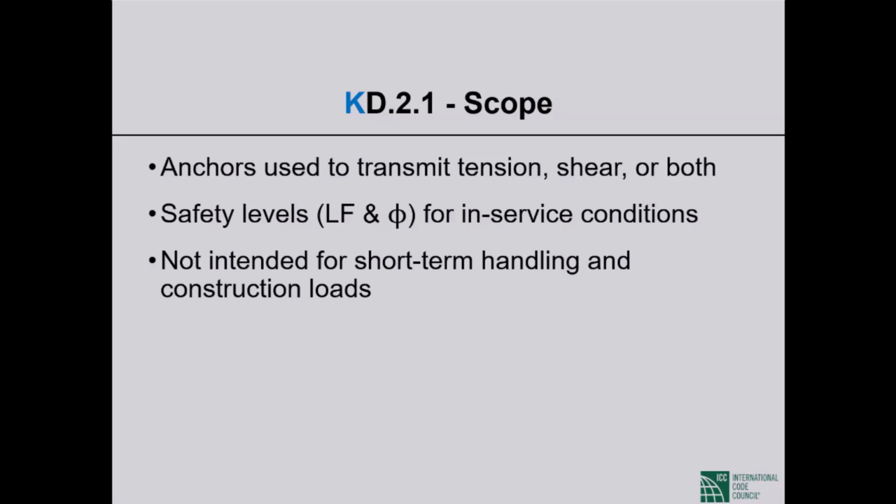Construction loads are not included in the scope of Appendix K. Neither are short-term handling loads. If you have to install anchors to transmit construction loads, you have to go beyond Appendix K to do that. That is not within the scope of Appendix K.